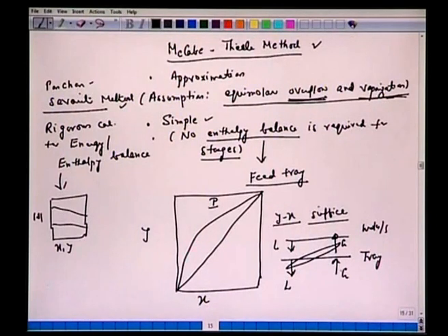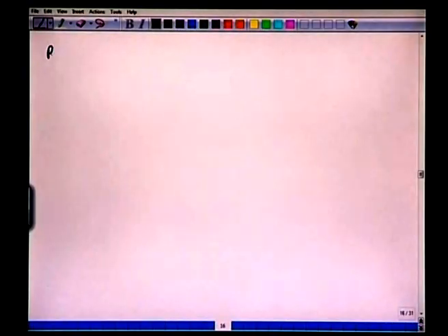So what is the basis of these assumptions? How does it evolve? From where do we get it? Let's focus here. If you recall, in the Ponchon-Savarit method, we had expressions for Ln over Gn plus 1. So the liquid which is leaving the tray n and the vapor which is arriving from n plus 1 or reaching this nth plate, the ratio of the two molar flow rates we wrote in terms of Q dash, the enthalpy of the vapor phase n plus 1, and we had Q prime over HLn.